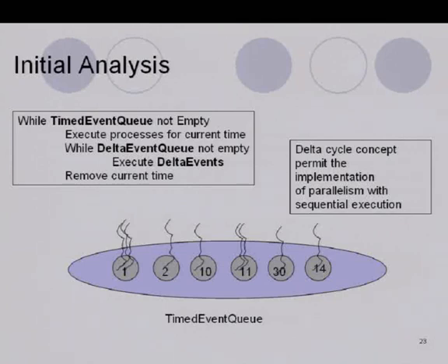So the engine basically goes through the queue for the current timestamp, takes out the event, executes all the threads. Whatever those executing threads do could actually make other threads become active, and it will go like this. When it's finished one element in time, it goes to the next element in time and executes like this. So it's a traditional event-based simulation.